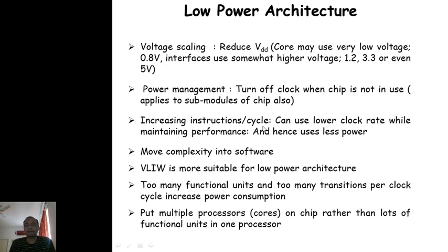But in an ordinary processor, if we reduce the clock rate, then the speed of execution also gets reduced. So if we have a sophisticated pipeline structure which gives performance beyond 1 instruction per cycle, say 2 instructions per cycle, and I reduce the clock frequency by 2, then I can achieve a reduction in power consumption. That technique is also used in modern controllers and DSP chips.